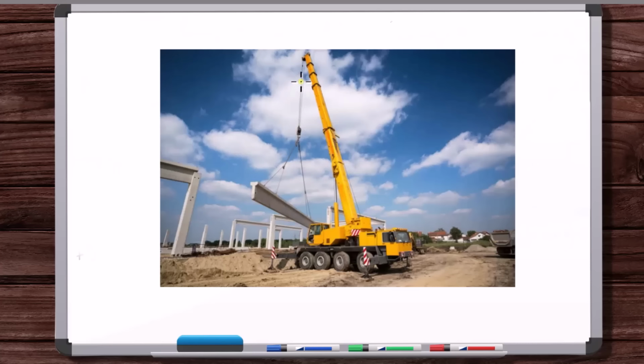And chains and slings always used to confuse me because they're not rigid. But remember, the idea is we could make a cut here and then make a free body diagram of just this. You would neglect the weight of the chain, of the sling, and put the weight of this concrete beam here at the center of mass. If you made this close to slack, with only like 5 pounds, you'd have this geometry of sling and concrete beam, right? Then once you lift the beam fully, you'd have that same geometry.